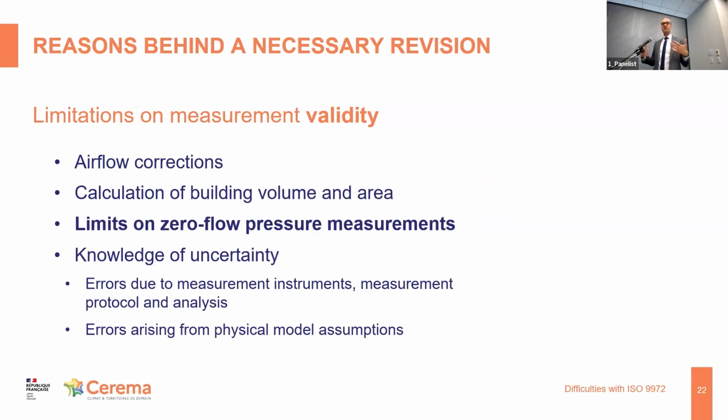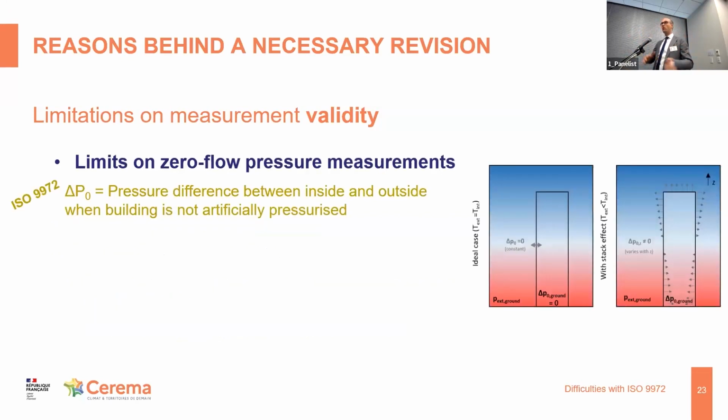Yeah, and then speaking of zero flow pressure measurements. Zero flow pressure measurements are the measurements done without pressurizing the building before and after the actual measurement. So it functions as a kind of baseline pressure before and after the building is pressurized. And as Ian and the previous speakers presented about high-rise buildings, there are very large zero flow pressure measurements due to stack effect.